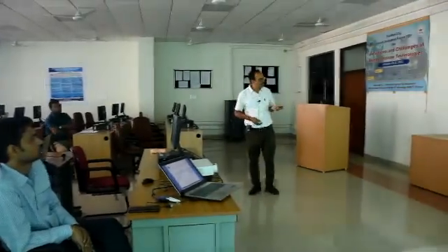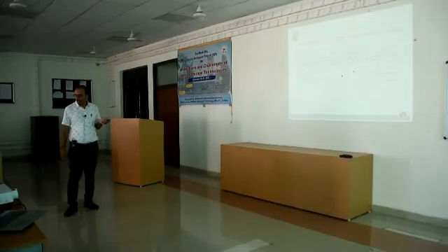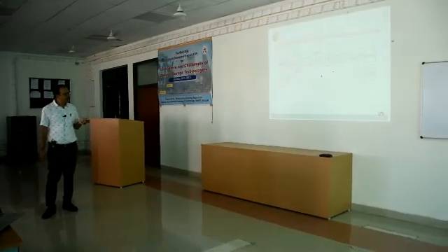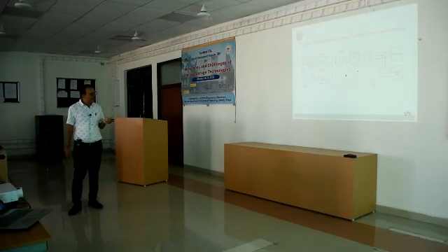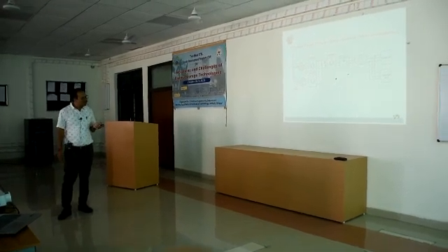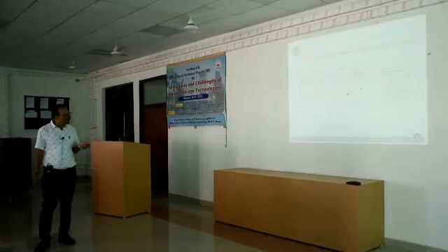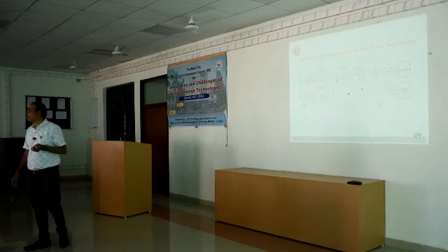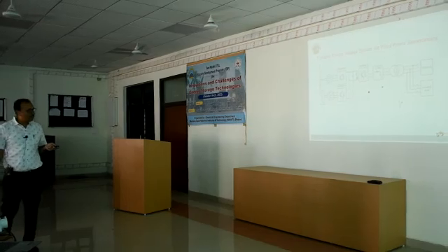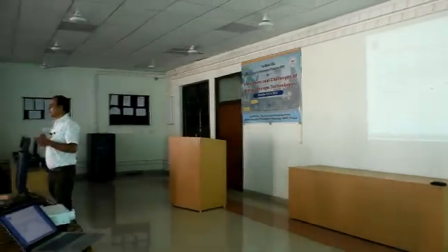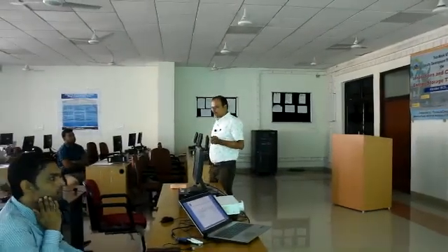Okay, so what is done in this case? This is your wind turbine connected with a generator, a synchronous machine generator. Then the first converter is there, another converter is there. These are part of this wind energy conversion system. Apart from that, they have used one more converter, and with this converter they are running an induction generator, an induction drive, which is connected to a flywheel.